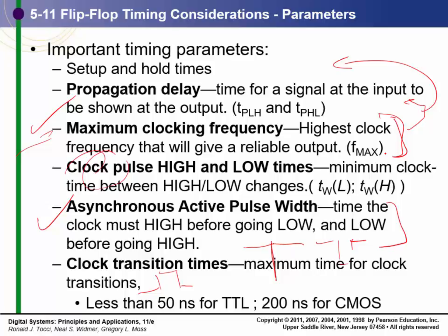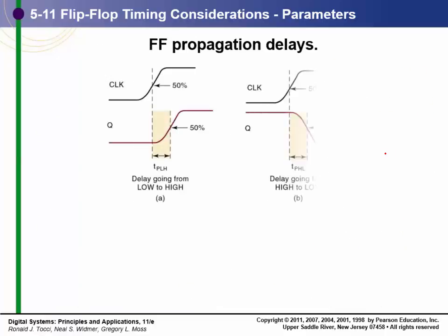But if I take that same design and put it into a Xilinx part, some routes might operate at 3 gigahertz, some designs will only operate up to 1.5 gigahertz, depending on how it routes. Same circuit, but just depending on how it routed it. So these are just timing parameters. I'm not going to be testing a great deal other than these are what they are.